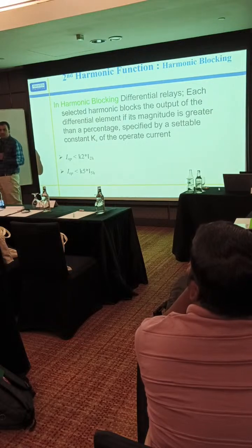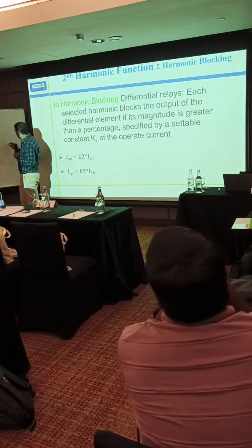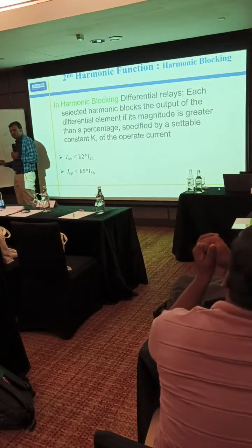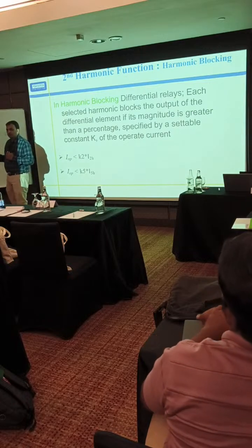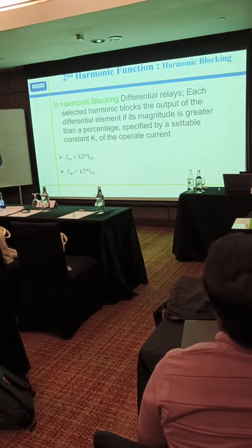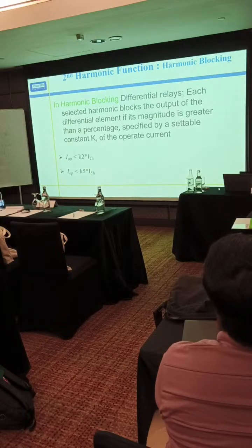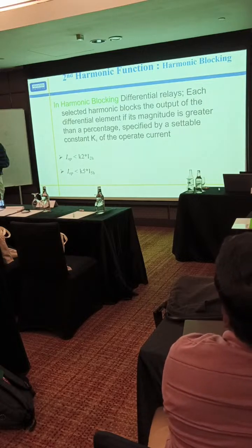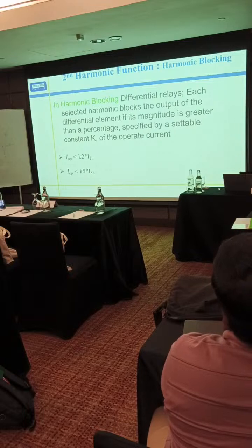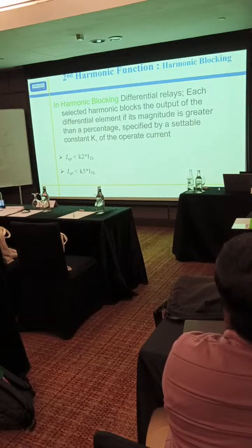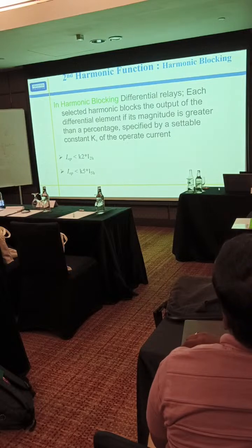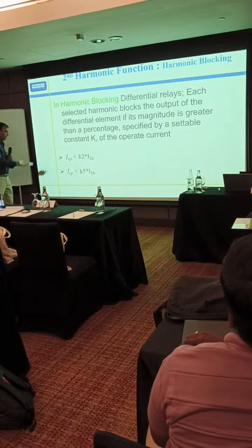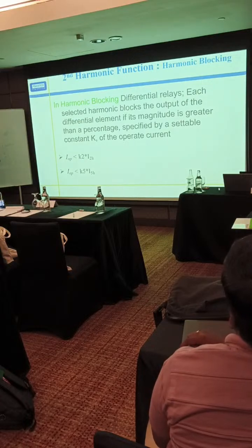So in this testing, we have to reduce the harmonic component so that it will come to the restrained region and be released. So we confirm that it is blocking for more than our setting, and unblocking at which point. Okay. So any confusion you can ask. And similarly for the fifth harmonic, testing is exactly the same.